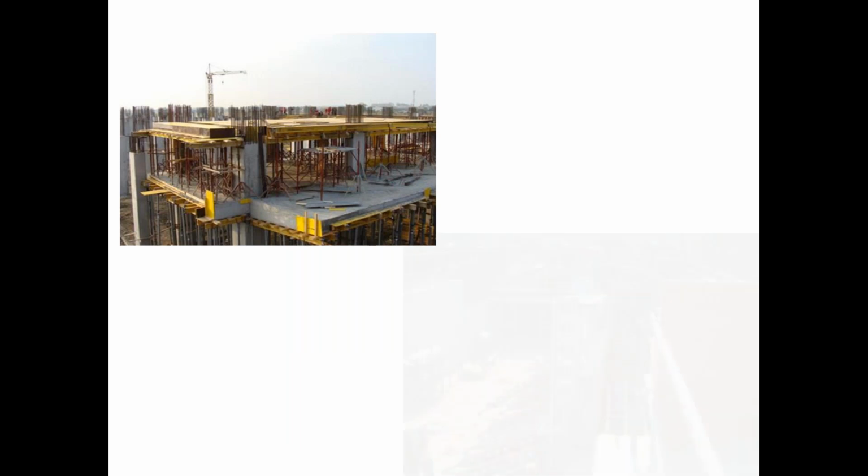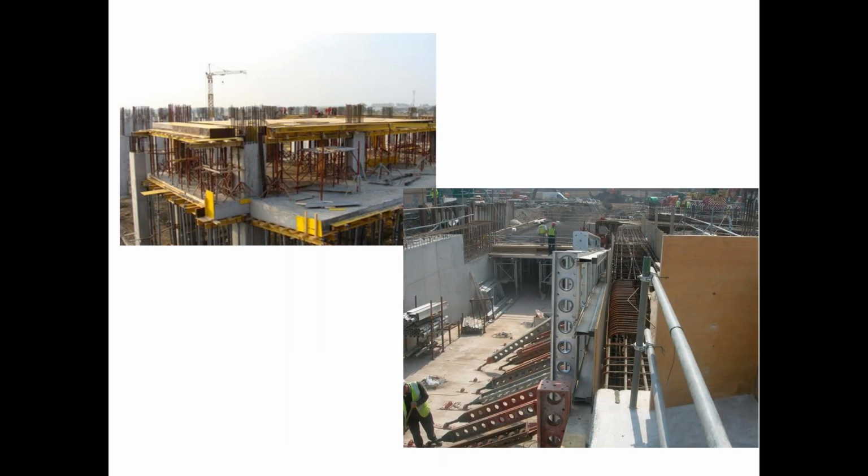This is overseas, in China, and what they're doing there on the left top is they put the columns up, then they put the scaffolding, put the forms all around, cast the floor, and as soon as they want to cure it pretty quick and get it nice and hard, and then they can take all that off, pour some more columns on top, and they just go stepwise all the way up. All right. And the one on the bottom right, look at how much rebar steelwork is in those walls behind that form in the middle there. It's an amazing amount of steel reinforcing in those. But it helps increase the strength and durability of the concrete and the toughness as well.